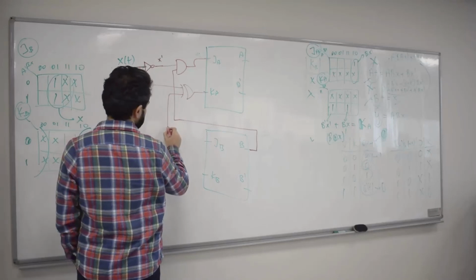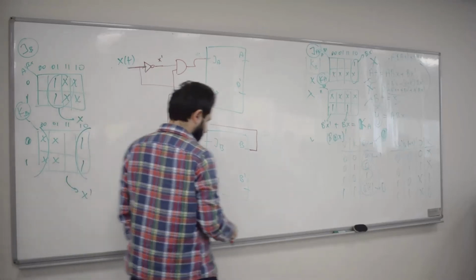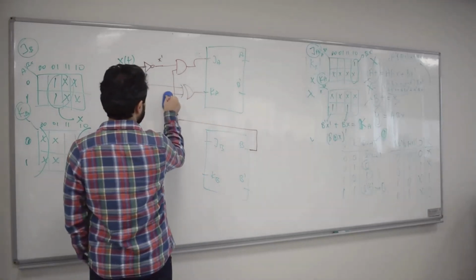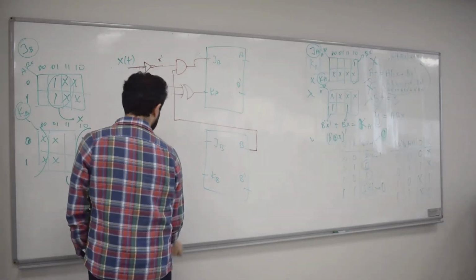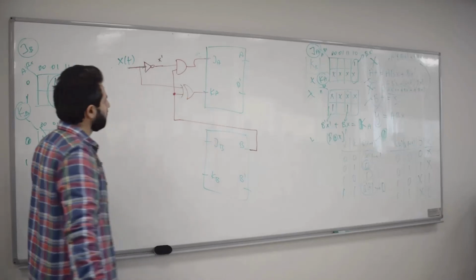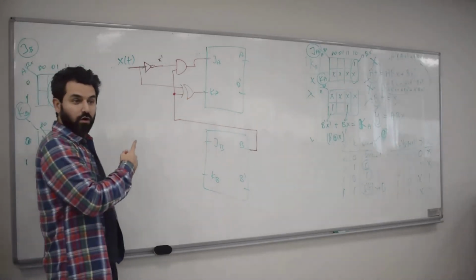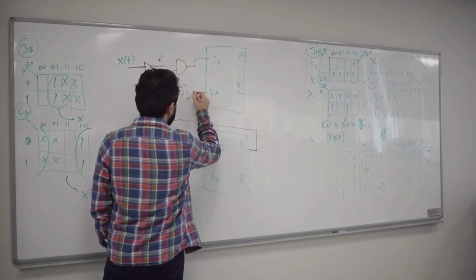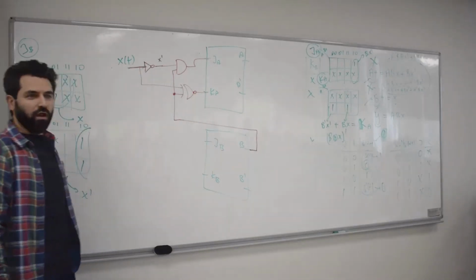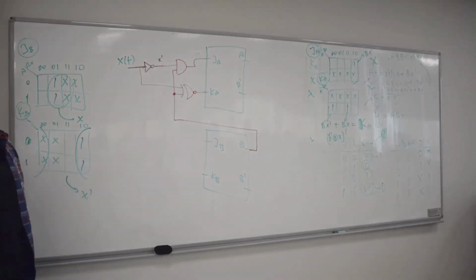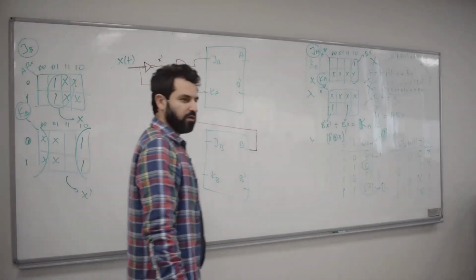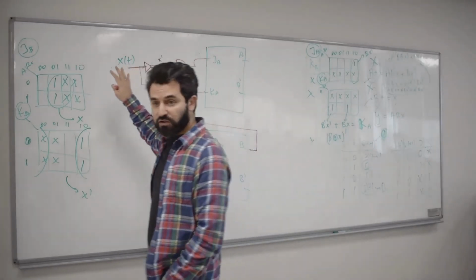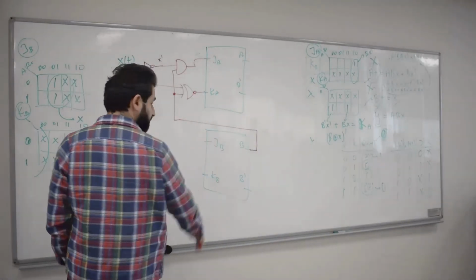And the other connection: I already have a B here, so I don't need to prolong my wires. Put just a dot here to connect it. But this is, of course, XOR, so I'm going to put a small circle to make it XNOR. It's pretty simple to make it XNOR. So I got an XNOR for KA. We're done with the first flip-flop. Let's look at the second flip-flop.